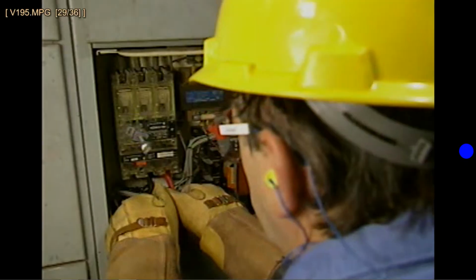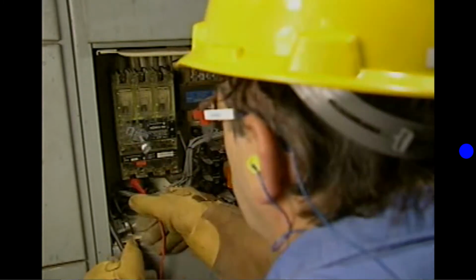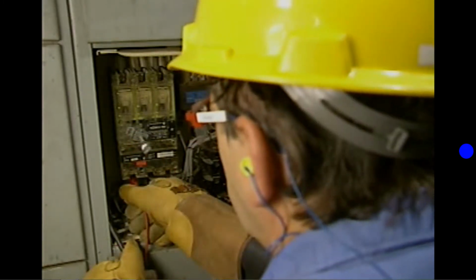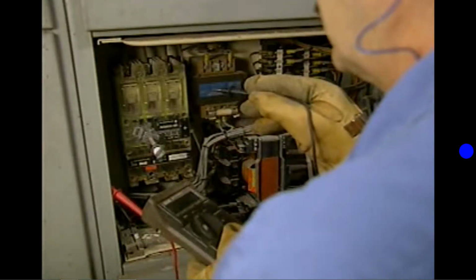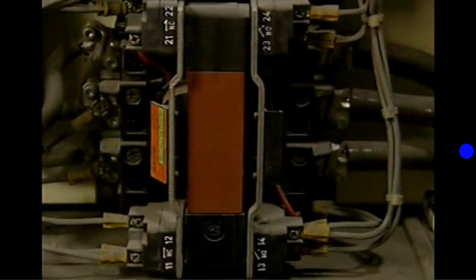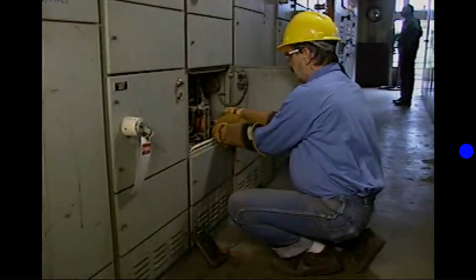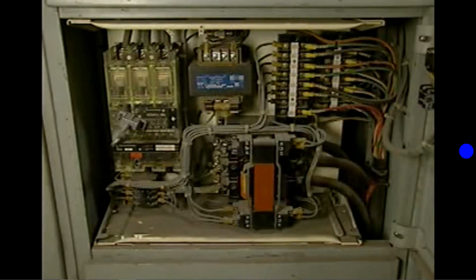In this example, the voltage tester indicates 0 volts on all phase-to-phase and phase-to-ground tests, which means that the breaker is de-energized. Finally, the voltage tester is used to test the incoming power line again to make sure that the tester is still working properly. In this example, the next circuit component to be checked is the motor controller. First, a voltage tester is used to make sure the controller is de-energized. The controller is de-energized, so the interior of the controller's housing can be inspected for dirty or loose connections.